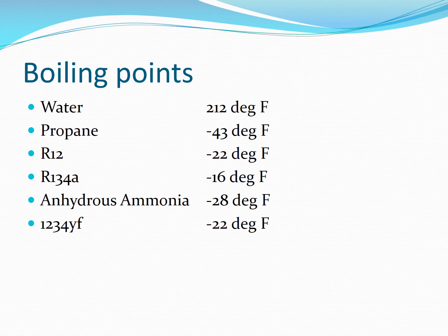Unfortunately, it would be very dangerous to use as a refrigerant, given that if you had a leak in the evaporator or a leak in the condenser, that could cause some very serious health issues if it was anhydrous ammonia, because it is oxygen depleting and a person would theoretically suffocate if you had an evaporator leak. Or it could be very flammable or explosive if you were using something like propane and you had an evaporator leak or a condenser leak in an engine bay.